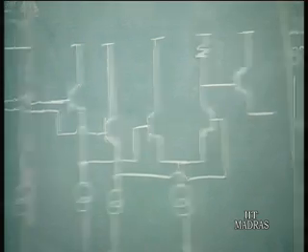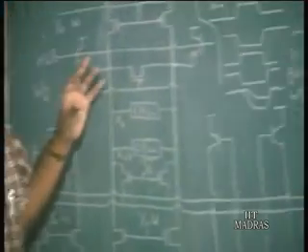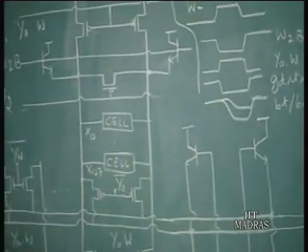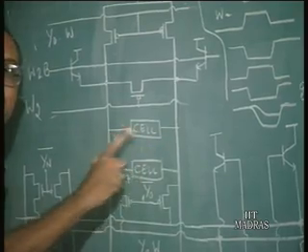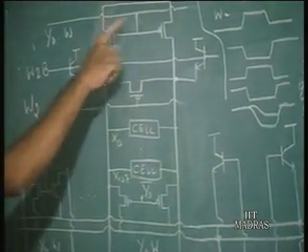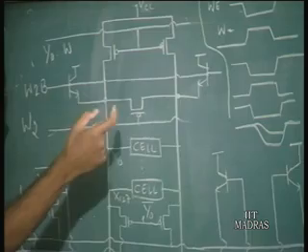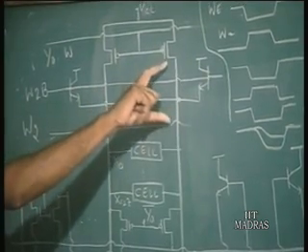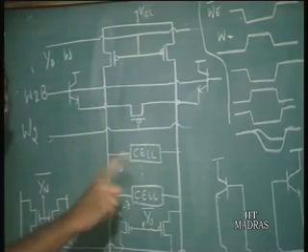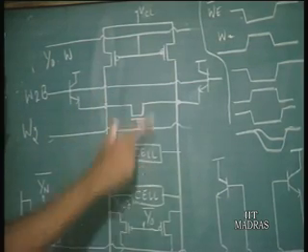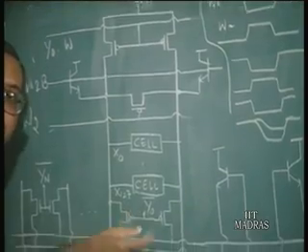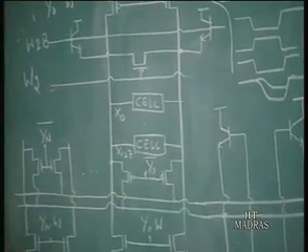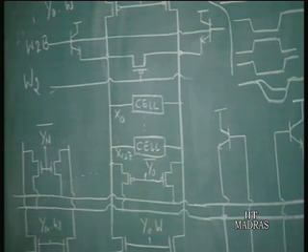Okay. So, you select one particular cell and that information is passed on to the output. The important point here is that with the help of these NMOS transistors, a low load resistance basically, you create a very small differential voltage between the two lines, only 90 millivolts. So, it is very fast, because although you have a large data line capacitance, the change in voltage is extremely small. That makes it very fast.